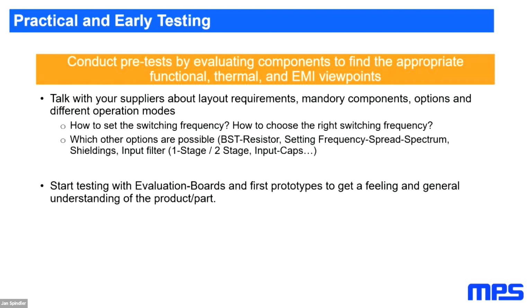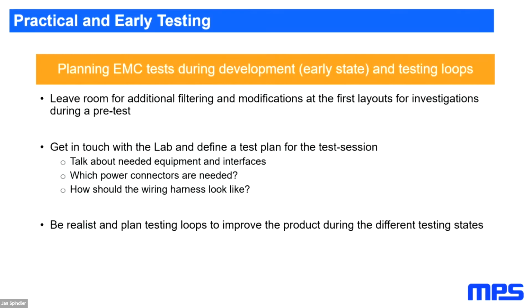And also the option of evaluation boards and first prototypes to get a feeling, especially before you go to a lab or external lab where you need to pay money. It would be good if you have a feeling about what you have in your hands and understand what you are doing. Planning the tests, as mentioned, leave room for filtering maybe in the first stage. Later, it's not necessary. It's also about cost reductions.